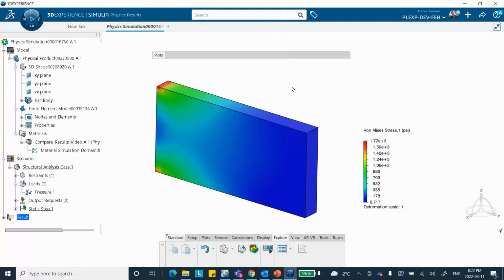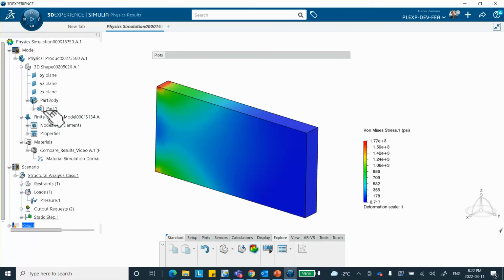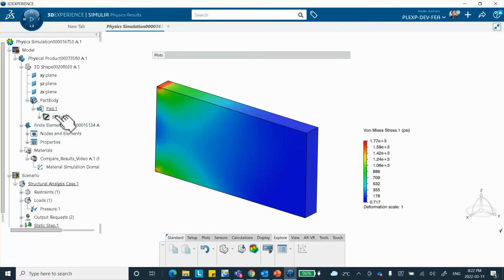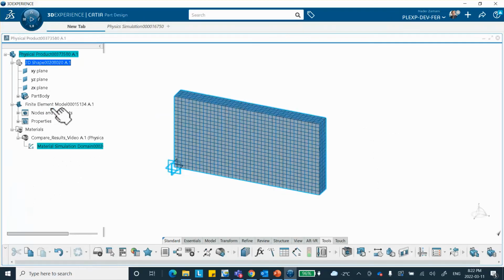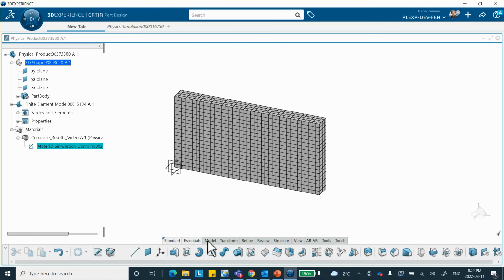Okay, now, so this is done. What I want to do now is to go and put a fillet here. So let's go to our part, which was here, our part, to that path. Okay, and we're going to put a fillet there. Now, what that means, the way I'm doing it, because of changing my part here, obviously my original part is modified.